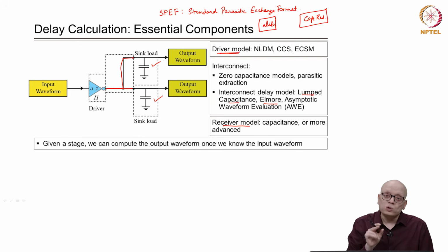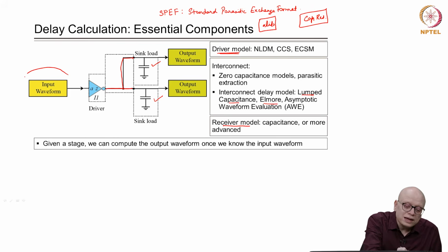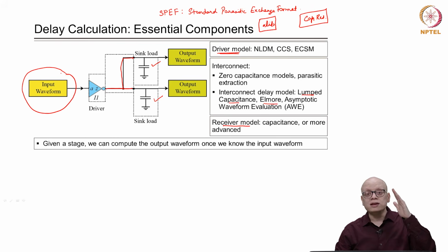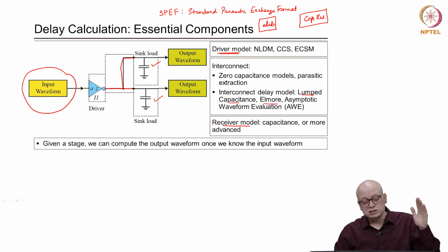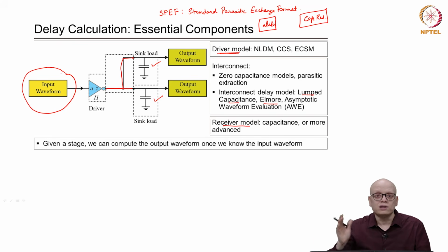However, to compute the delay, the tool will also need one more piece of information, that is the input waveform. For example, if the slew is very steep, meaning that the input waveform is rising very fast, then the delay will be smaller and so on.